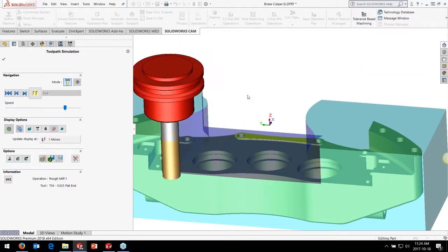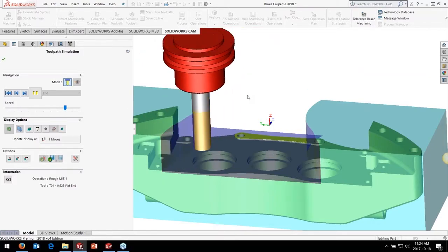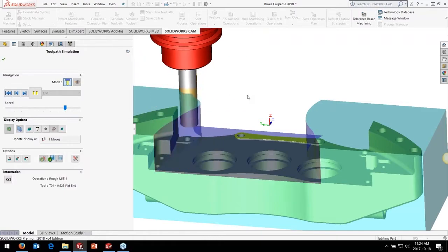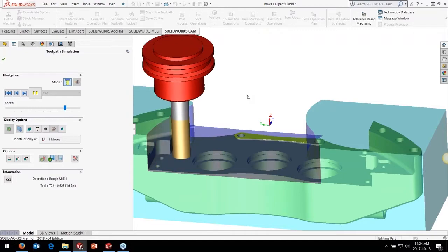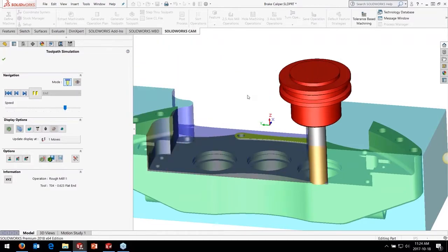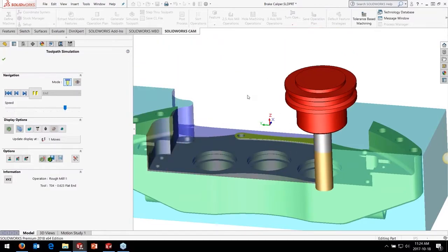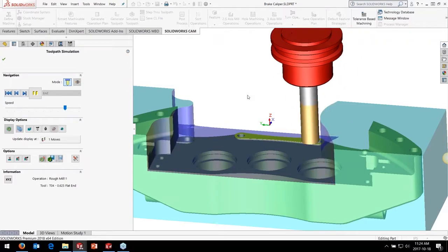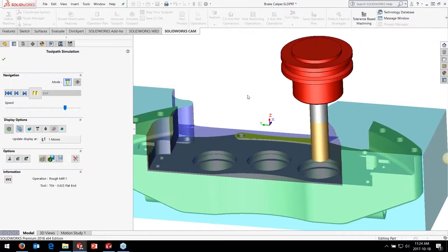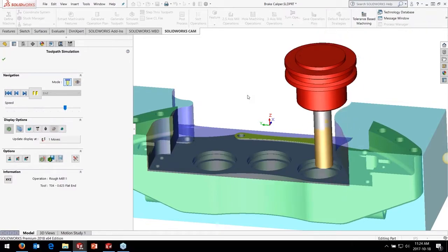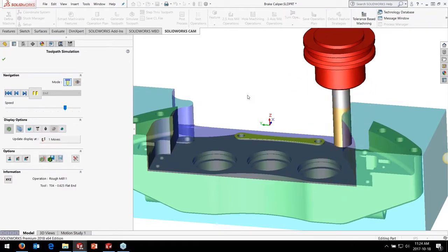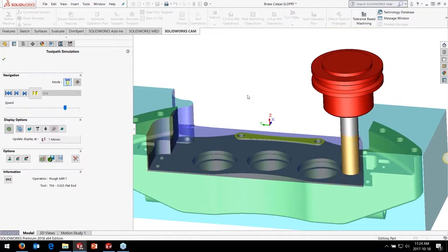Now what it's actually going to do is, as it's coming into the material line and it comes in on the opposite sides here, it's going to actually slow the feed rates down so you don't get that shock on the tool. If you've ever started a grinder or anything like that and gone into the material and it bites, that's basically you're taking a part and taking a tool that's spinning at 4,000 RPM and basically going into static material.